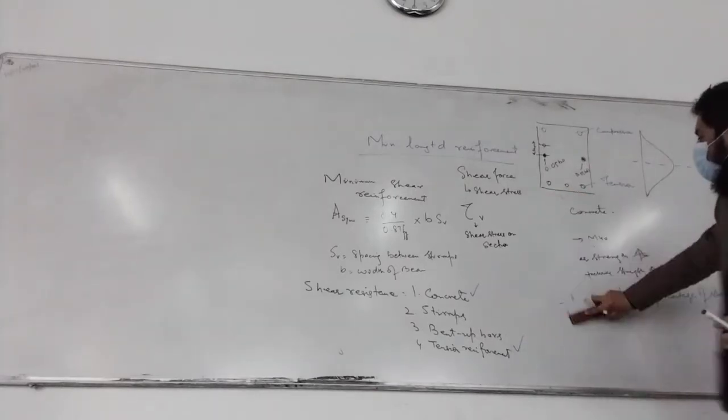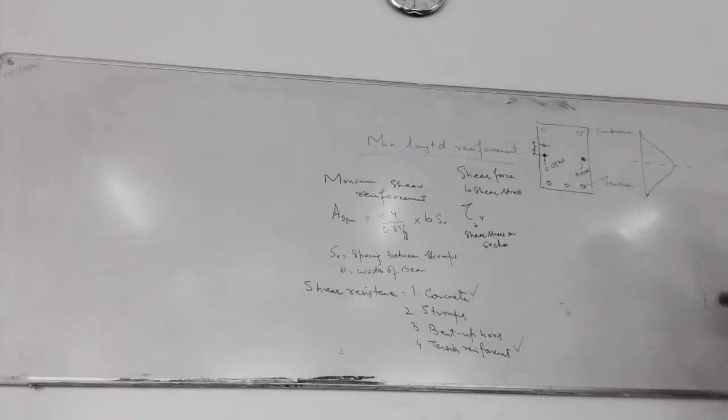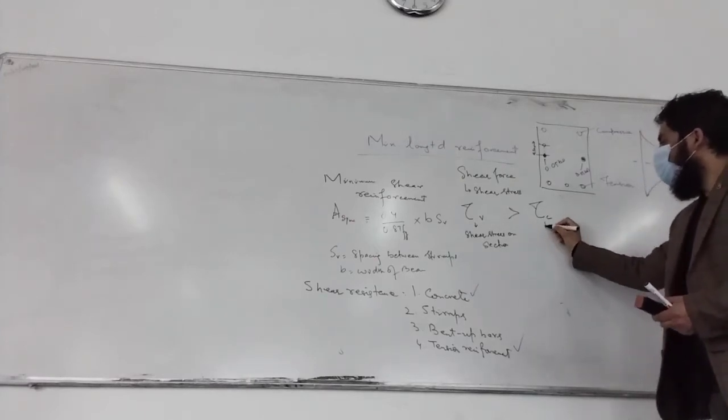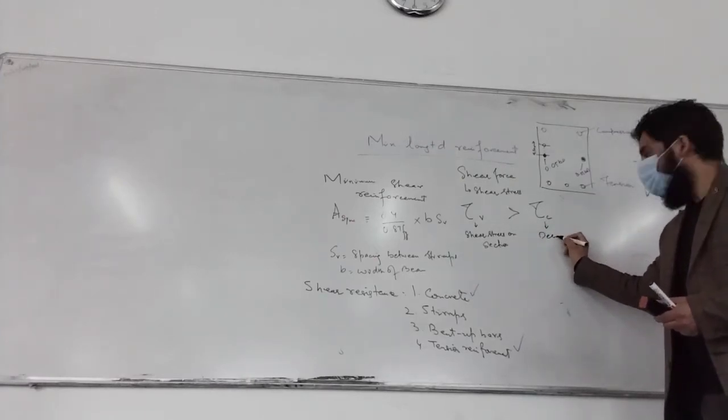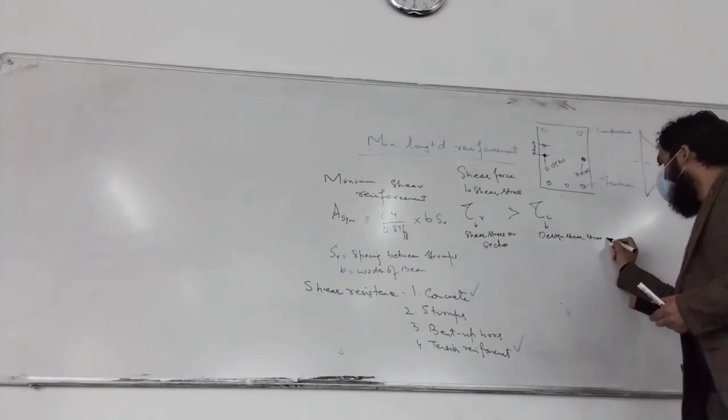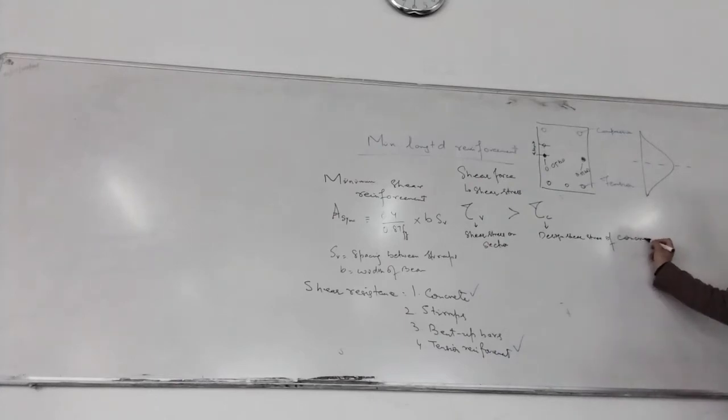If this is greater than tau c, this is design shear stress of concrete, then what do you do?